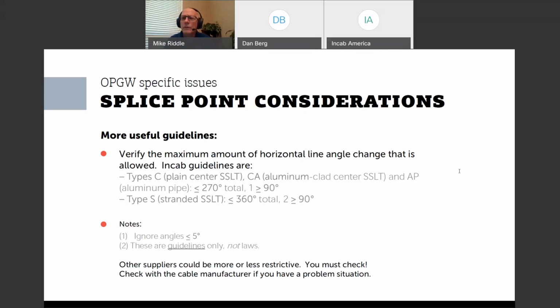Would you recommend short lengths of cable for a proper, easy installation? 20 to 20,000 feet is no problem. And you're eliminating splice points. We do have some customers that use 7,000 foot reels, and maybe for them a 10,000 foot reel is long. We don't mind, but there's no reason that you can't go 20, 25,000 feet.